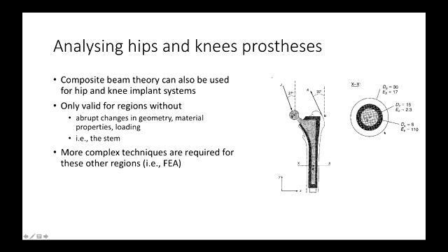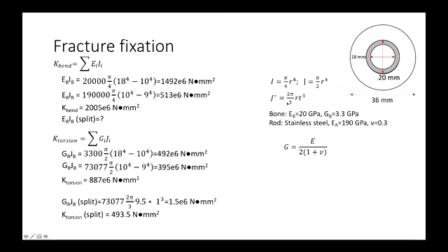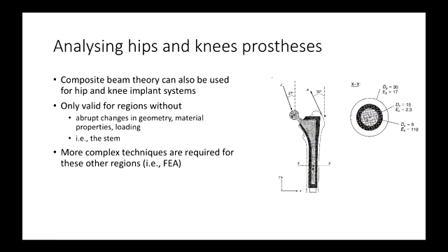So again, you've got these 3 different materials, right? So then you can do that same calculation. Calculate what the stiffness is. If you had a force like at J, using the free body diagram, you could calculate your moment at section X and then calculate the bending stiffness or the bending stress. Okay.